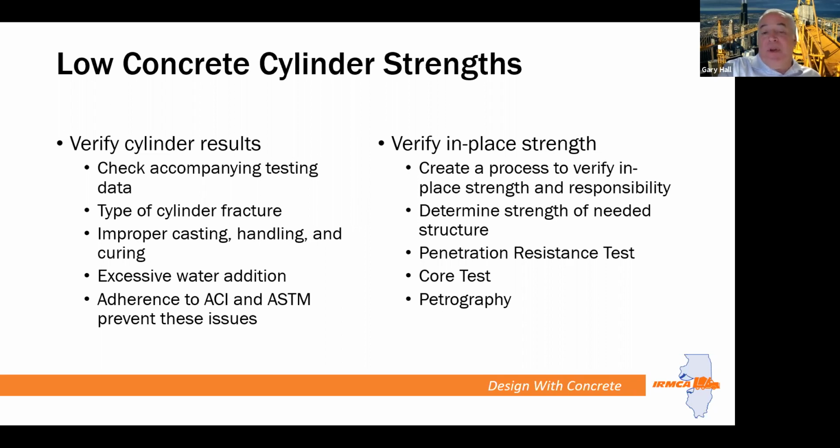In the event that we do have low cylinder breaks, we have a number of standards that are provided, or recommendations in terms of investigating low cylinder results. First of all, we have to take a look at the statistical analysis, because low cylinder breaks actually result in low average cylinders, because we determine that by a running average of 3 breaks.